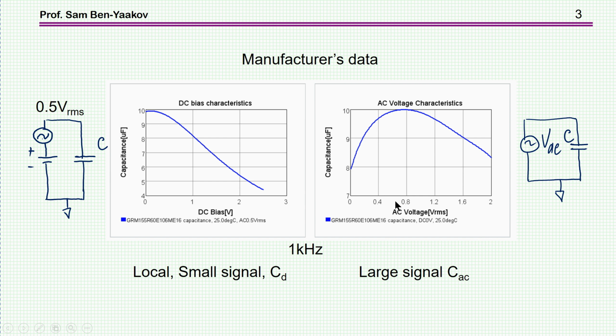Here it's changing. At the beginning, it's a small signal, then it's going up and up and up. And say this point here means that the signal was 2 volt RMS fed to the capacitor. The current is measured. And from these two values of the voltage and current, of course, you can calculate the capacitance, which is shown here.